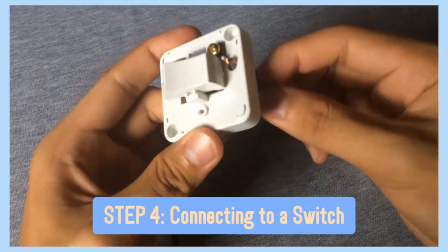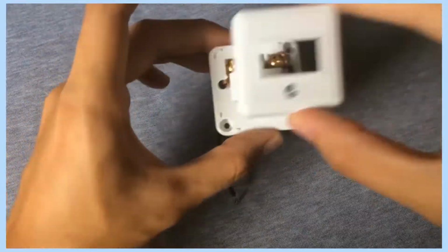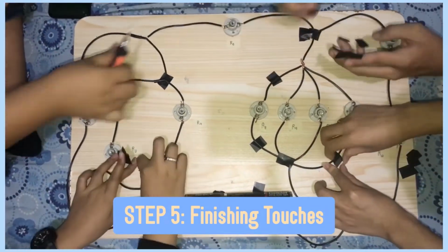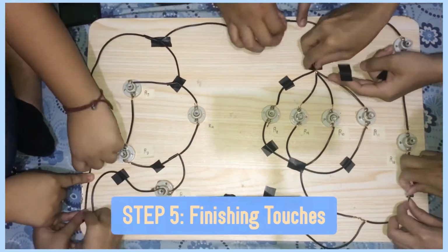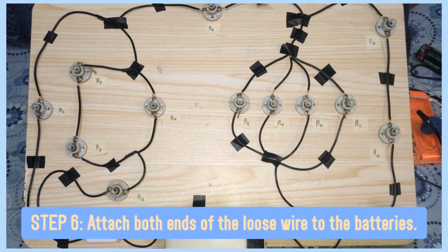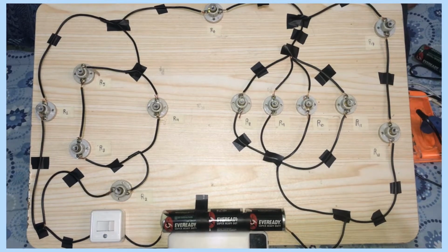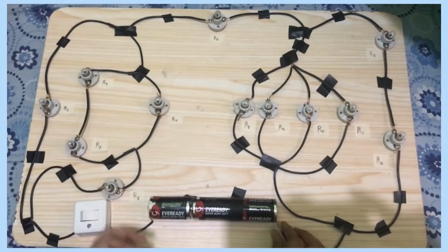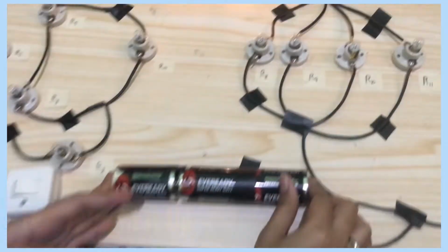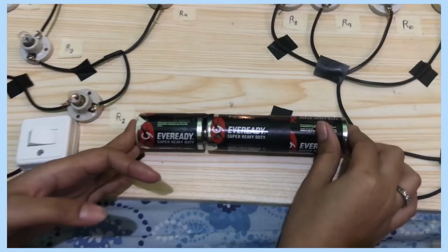Step 4. Connecting to a switch. Now we open the switch and start to connect the negative and positive wire for it. Step 5. Finishing touches. Now after we make a model, we put masking tape or electrical tape on these wires to make it more neat. Step 6. Attach both ends of the loose wire to the batteries. Connect one side to the positive side and the other side to the negative side. Step 7. Light it up. Start to light up these bulbs and experiment with the parallel and series circuit in the conditional situations.